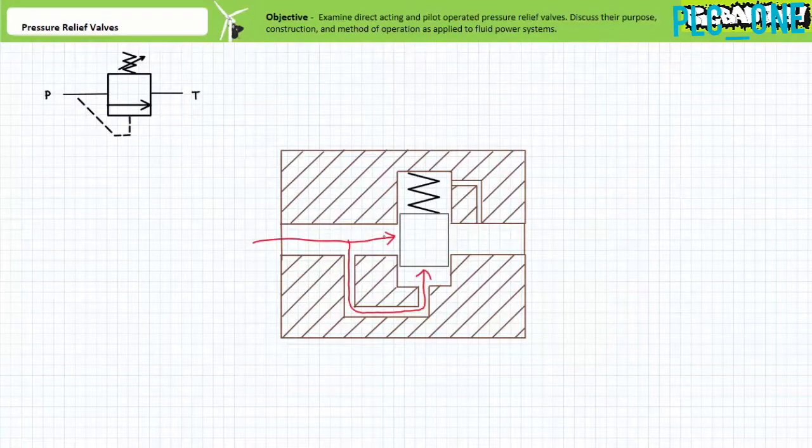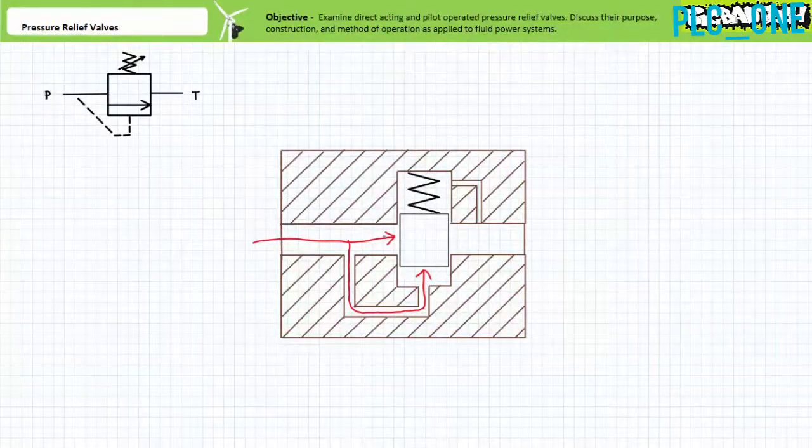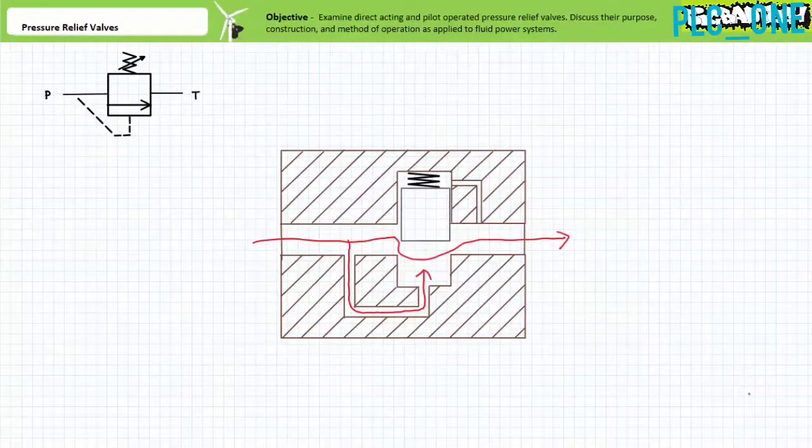Given the pilot passageway senses pressure on the upstream P passageway, and Pascal's law states pressure in a confined fluid is exerted undiminished in all directions, pressurized input acts on the bottom face of the moving piston. When pressure-induced force on the bottom of the moving piston exceeds that of the biasing spring, the moving piston is forced upwards, opening a passage from P to T.